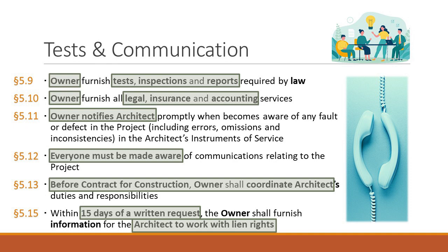You need to provide proper notice if the owner becomes aware of any fault or defect. Now, the becomes aware is important because it's not obligating the owner to seek out fault or defect in the project or the errors in the drawings. It's if they become aware.